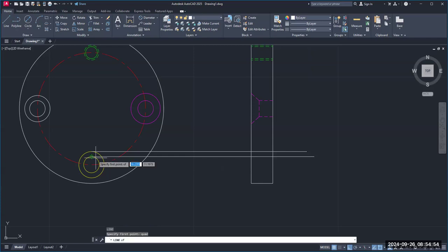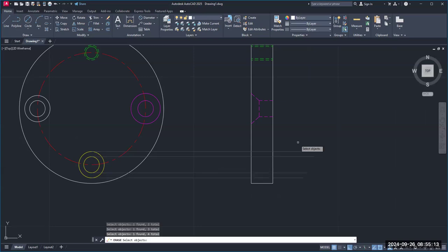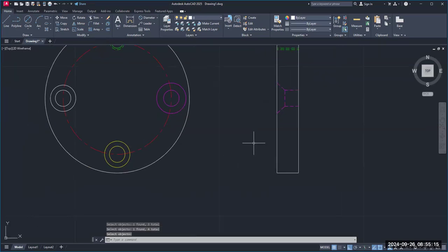I don't have to keep doing what? Typing the letter L. Enter, enter again. Notice I didn't have to type enter, enter. Okay, now I'm going to do this again just to show you. E, I'm going to erase all those lines. We do it twice because we want it nice. Watch. I typed in the letter L, quad, clicked, drag, click, enter, enter again, quad.